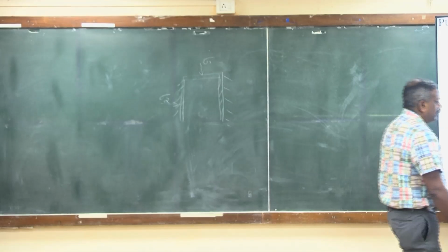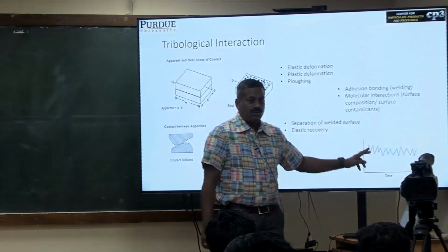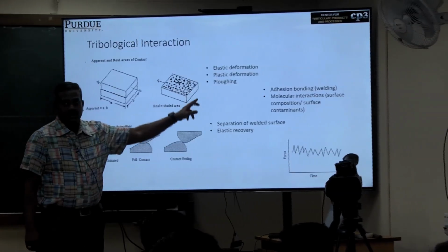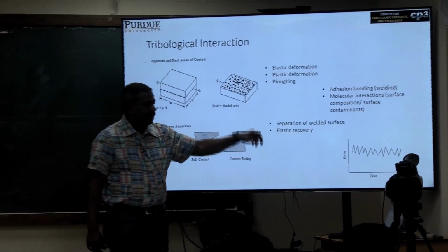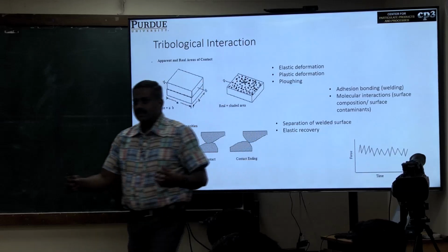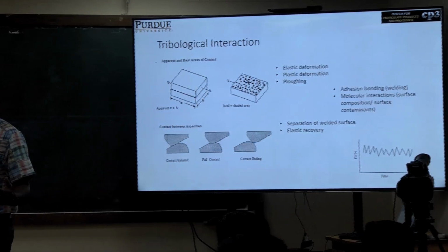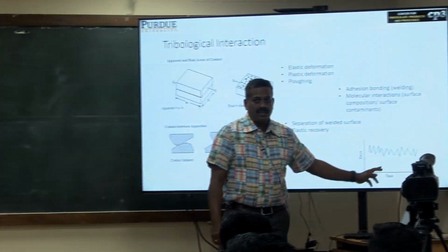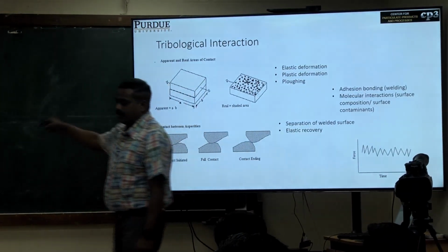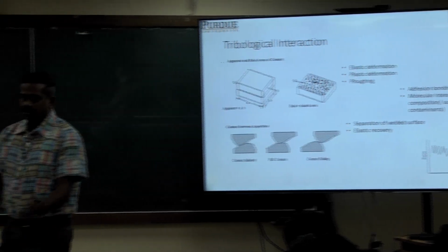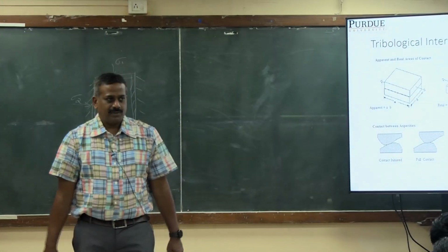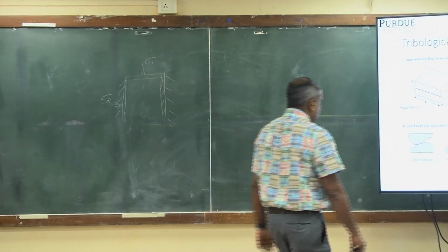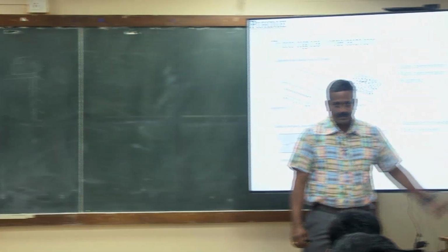In general, if you take a closer look at time and force, you will see a stick-slip motion due to tons of different asperities present on the surface of the material. It sticks, there will be bonding, then it slips, the elastic deformation is regained, and then again it sticks, slips, and so on. Just as an example, if a tire moves on the road surface, there will be continuous stick-slip motions occurring on the surface of the material. Okay.